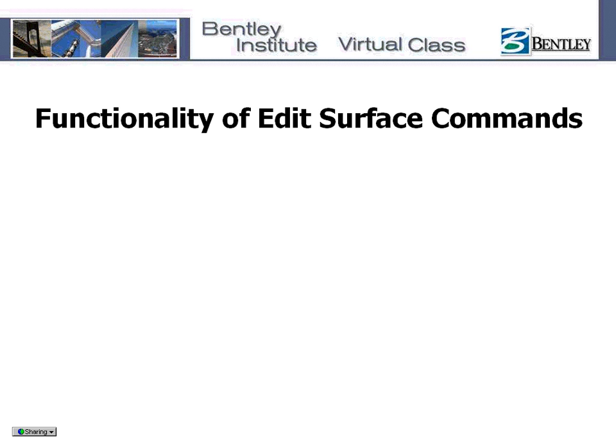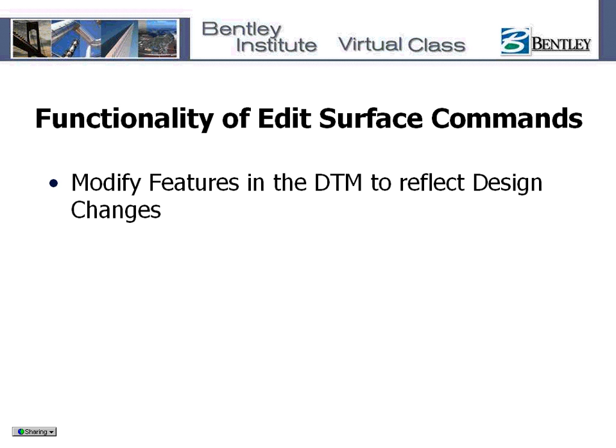Functionality of the EditSurfaceCommands. Modifying features in the DTM to design and reflect modifications through the course of a project. Speed up the design process. This is a huge advantage of EditSurfaceCommands, as they eliminate the need to display the feature, then edit the feature graphically with a MicroStation command, then delete the old feature from the DTM, and lastly, re-import the modified feature back into the surface and retriangulate. Long story short is that these tools save you time, thus they save you money.